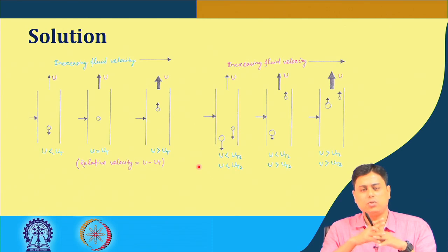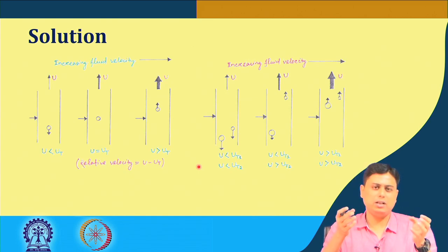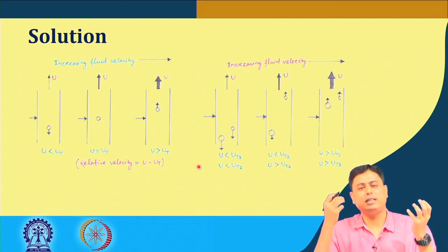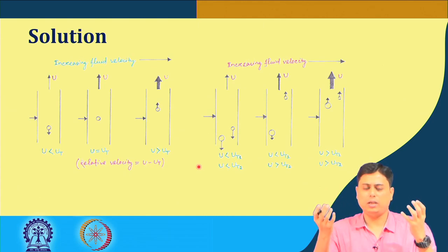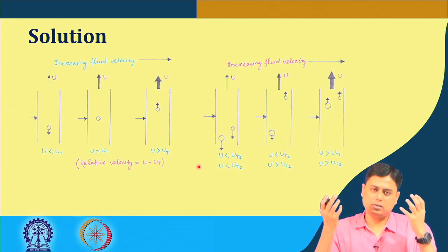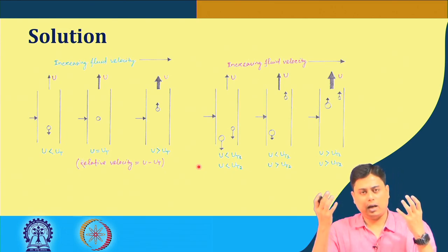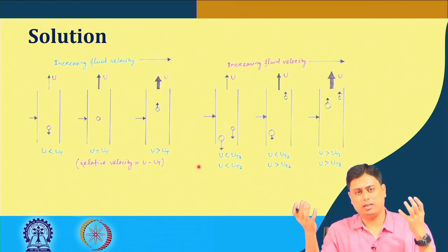So the bottom line is that we must avoid overlap of the terminal velocity ranges, since there is a range of particle sizes and two different densities. So we have to think of the two extremes. There is a heavier material and a lighter material. Heavier material is A, lighter material is B. Consider the heavier material with the smallest size, and the lighter material with the bigger size.